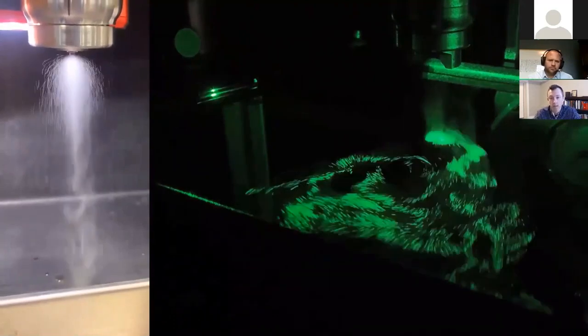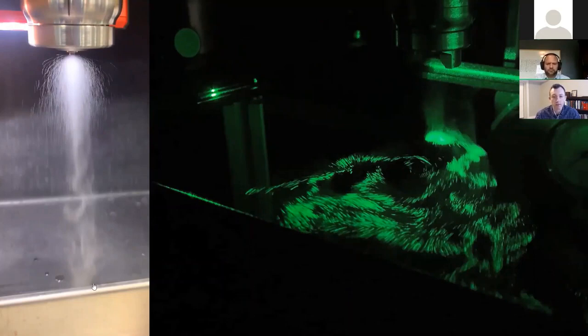Yeah, so it's a little hard to see, but you can see the nozzle itself in the top of the image there. You can see one, especially on the right-hand side, of shaping air, where there's air that comes out that pushes the fluid down towards the target, right? And so the atomization is happening due to the ultrasonic spray. So you're getting a nice fine droplet spray, a very uniform droplet size, not monodispersed, but a much tighter distribution than you'd see from a hydraulic spray or even a typical air atomized spray.